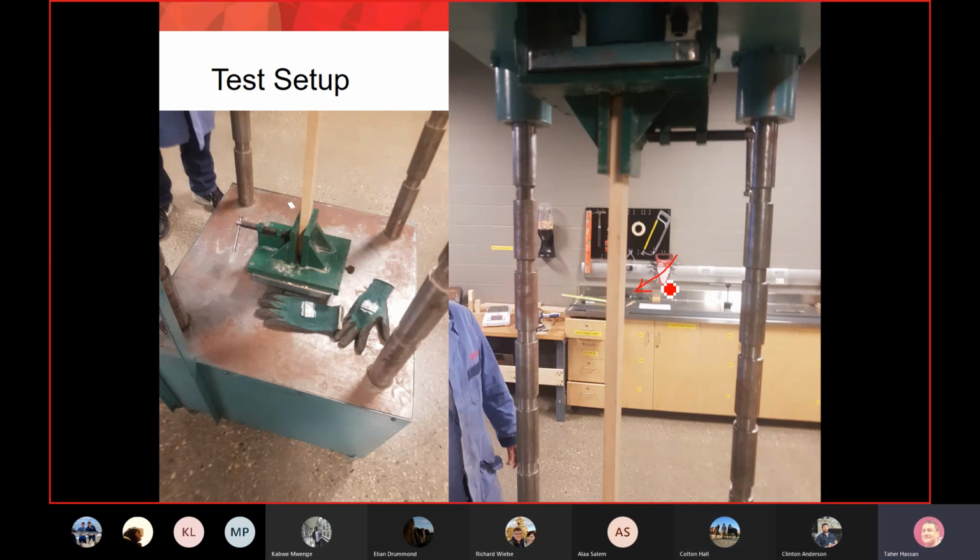So we're taking a small bit, maybe 4 feet or 5 feet high wood stud. You think of it as a wood stud. And then we put it in this machine. The machine is very old, but what it does is simply apply compression on your column and see what happens. The reason why we choose wood is that it is so elastic, so we can simply demonstrate this phenomenon, and we can use it over and over again. Once our column buckles, we just remove the load and then we use it again.